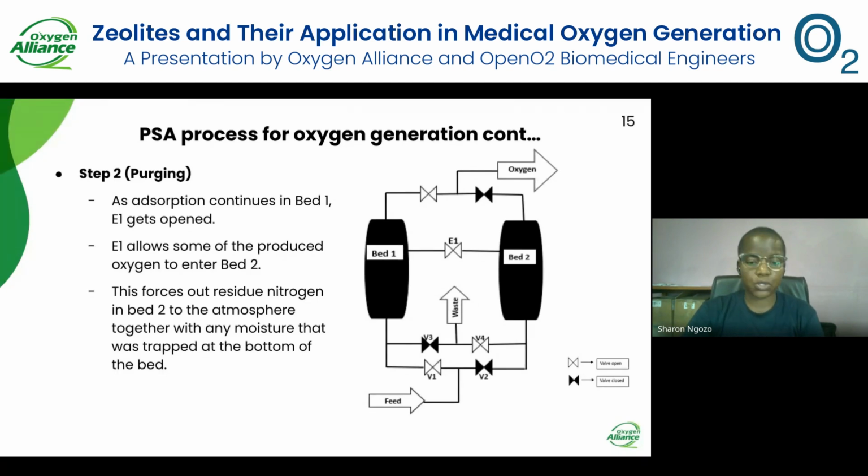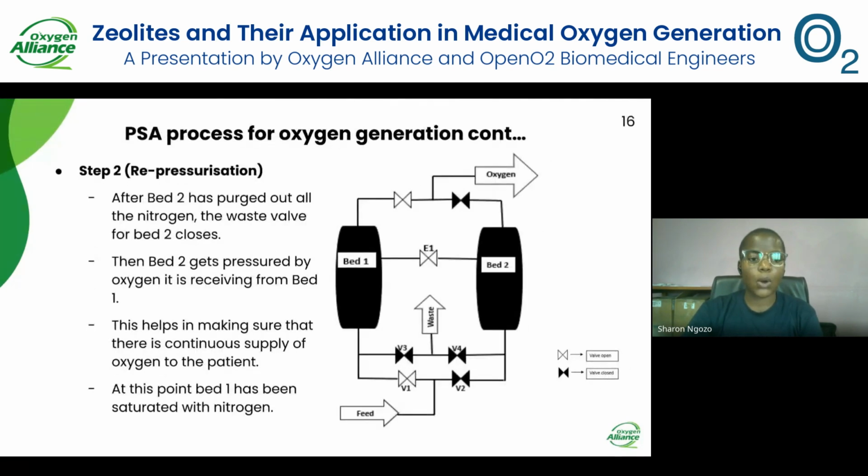As this process comes to an end, we now experience the repressurization. At this point, E1 is still open, but now V4, our waste valve, is being closed.